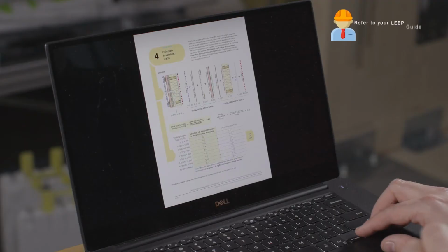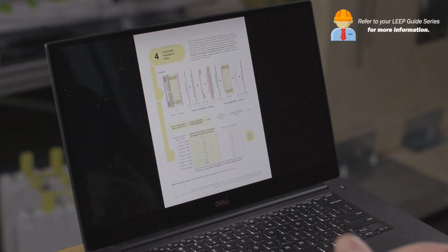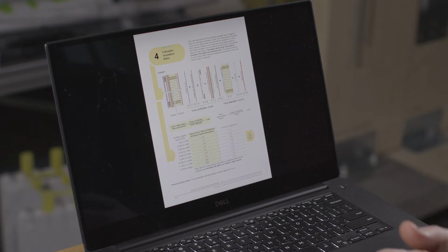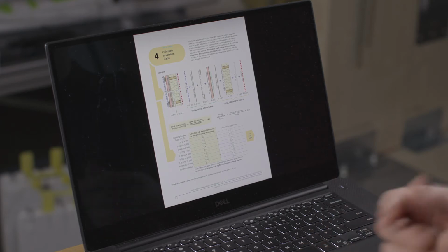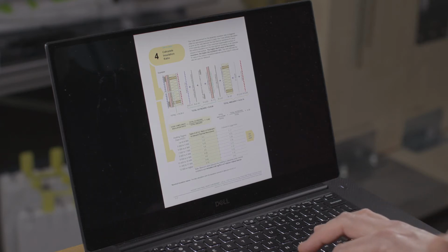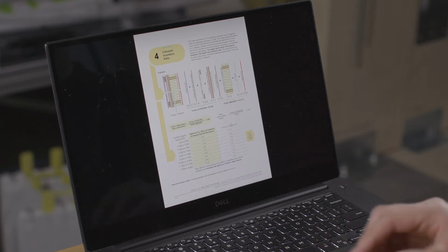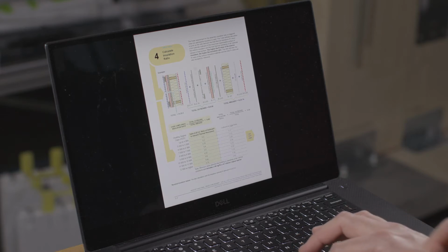Okay, so we've selected our insulation based on permeance. We're then going to look at the insulation ratio. And the reason we're looking at the insulation ratio is we want to look at the outboard to cavity insulation ratio. If you run through the calculation here, what you're looking for is how much exterior insulation you have, and if you can, get enough exterior insulation that you potentially don't need a vapor barrier on the inside.